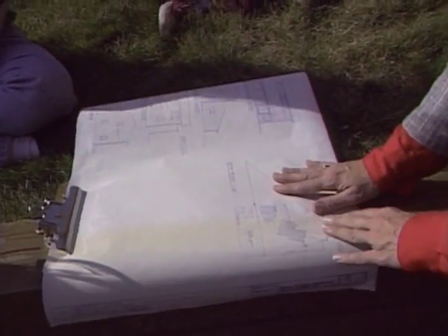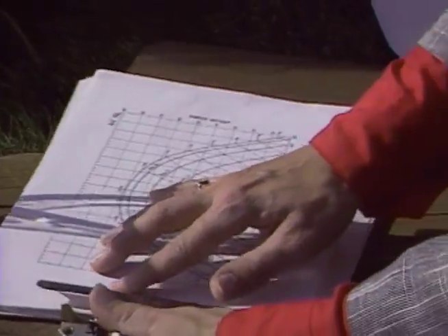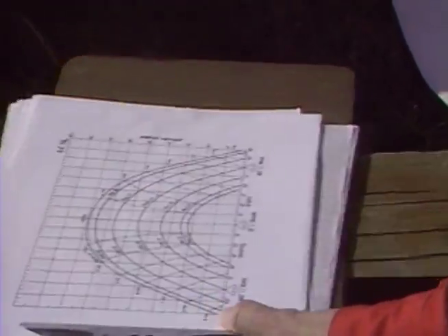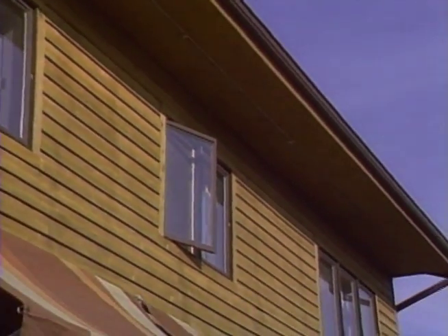All right, a passive house has to rely on how it's oriented to the sun, because the house itself is going to collect the heat. So it has to look as much at the sun as possible and have as many windows as it can to the south. Then, looking through a chart of the sun's path across the sky, the architect sees that nothing will shade the south wall in winter. A wide overhang keeps the sun from overheating the house in summer.